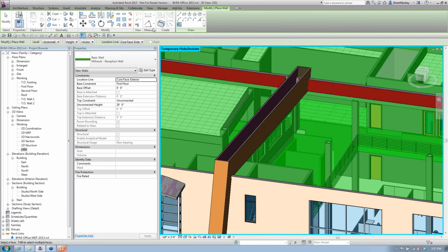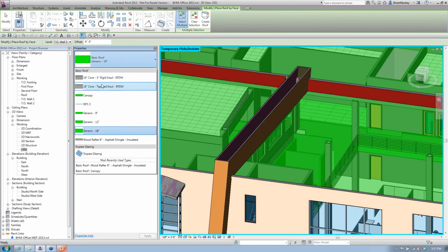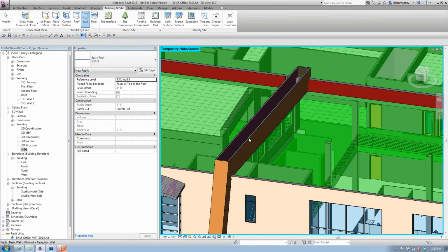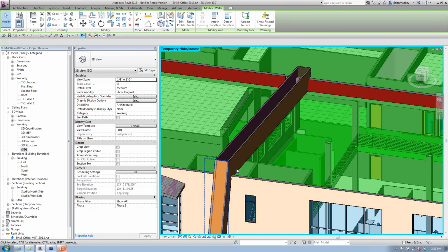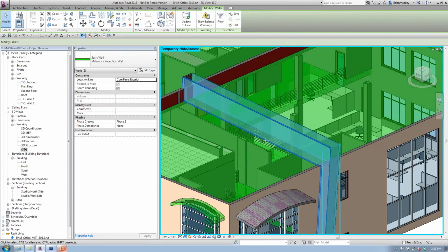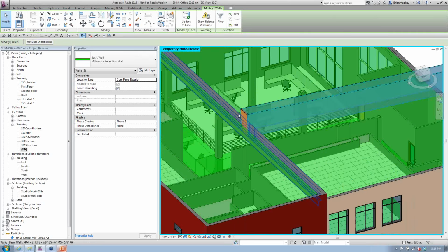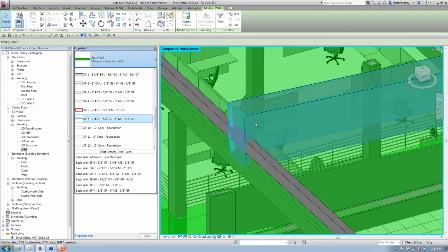And then once I get all those walls selected, for all the spaces selected for the walls, again, I could then switch to my roof type. So I'll go back to my massing in site and do a roof by face. Probably can choose the correct roof this time. And we're going to go ahead and put it on the face of that mass. Okay, I'm going to grab these millwork walls because I wasn't paying attention. Let's try hover tab. Come on, grab those, grab that. Grab this one. Ooh, I forgot to create my roof, so my roof didn't get created because I forgot to hit the little button that says create roof like I always do. Okay, we'll change those from millwork reception walls to my exterior wall type that is the blue one like it was.